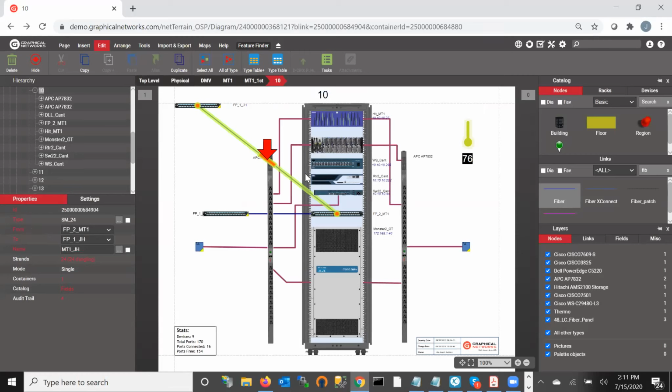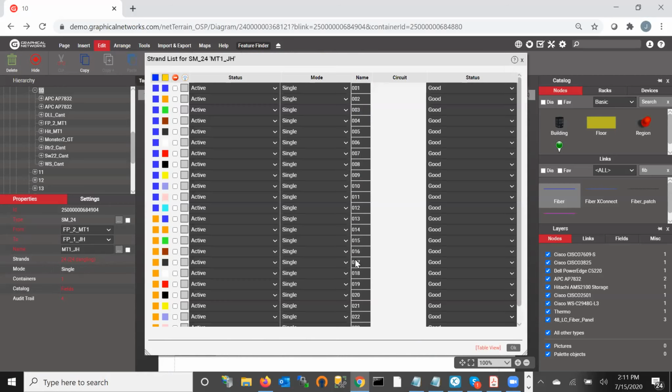to see that. So when I select the cable, cables for us can be individual connection points, or they can be cables that create or show strands, like strand interface. So for instance, I have a cable here on the left-hand side. I can click on it and it shows me the interface for that cable. And it shows me whether or not the strands themselves are connected. In this case, none of these strands have been connected yet. So it shows me the color of the buffer tube, the strand color.